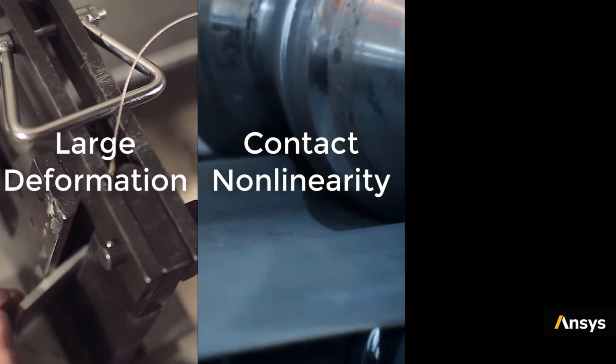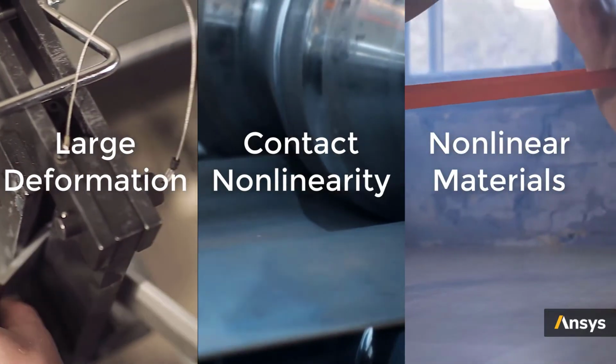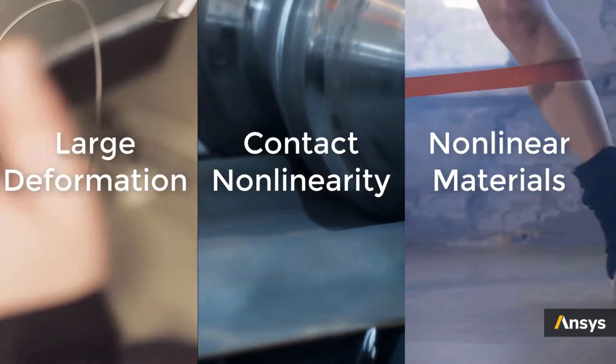Typically, there are three main factors that can change the stiffness of a system. They are large deformations, contact nonlinearities, and material nonlinearities. There are other special cases which can trigger a change in overall stiffness, but we'll discuss them towards the end. Let's start by focusing on the first factor, which is the large deformations.